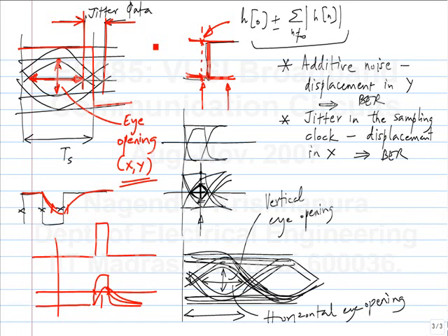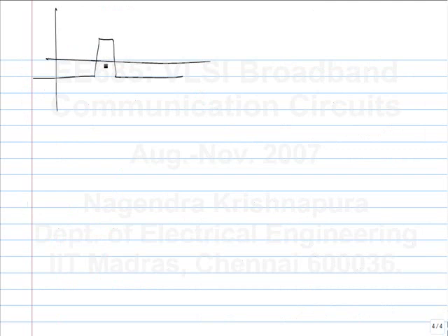Well, yeah, that's true. Here I'm looking only at the receiver clock. So the way you generate the data, there are many things that could contribute to jitter. Maybe the clock that you use to generate the data, that is jitter. The intersymbol interference as it goes through the channel, that is jitter. So jitter is like noise in that everywhere you will have it. Everywhere it will be present. Maybe it is present to smaller or larger extents, but there is no jitter-free clock, just like there is no noise-free signal.